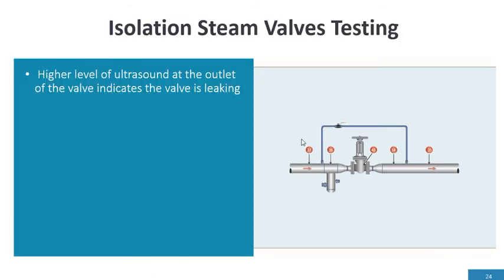Now here's a measurement: upstream 26, downstream 27, downstream 25, downstream 34, and at the valve 45. If I plotted this, it comes to 26, and then spikes up to 45, comes back to 34, and comes back. So this tells me this valve is leaking because of the high measurement here.